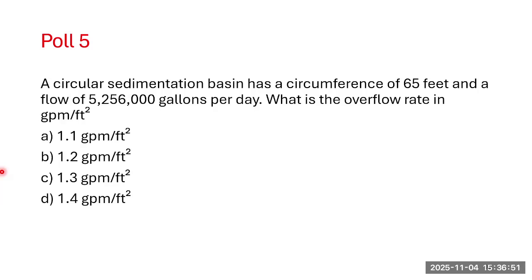Sometimes granular activated carbon can be added as an intermediate layer in a sand filter. The only caveat is it's not something that can be backwashed forever. You would still backwash the filter, but the granular activated carbon would have to be replaced at some point. So it makes more sense to have it as a separate unit as a polishing step after sand filtration.